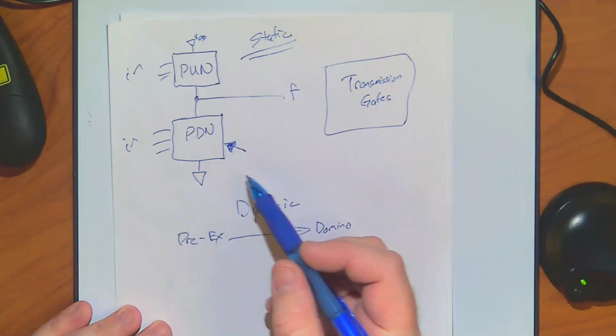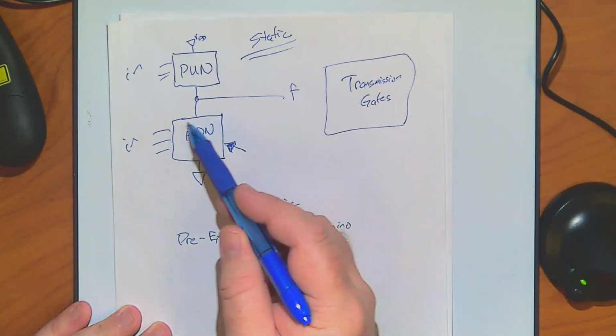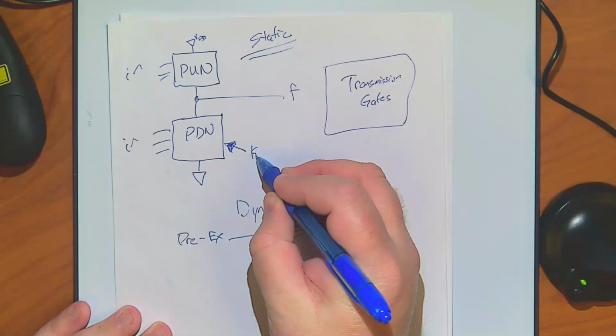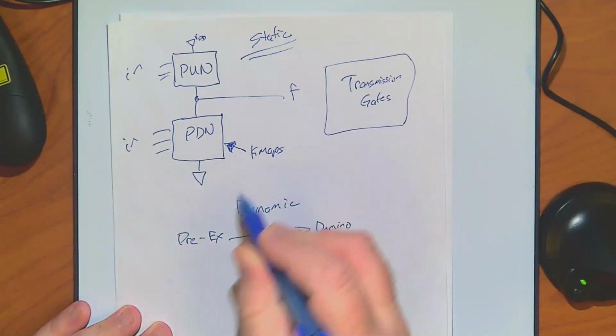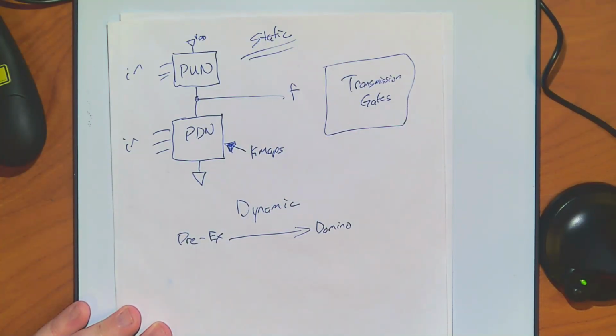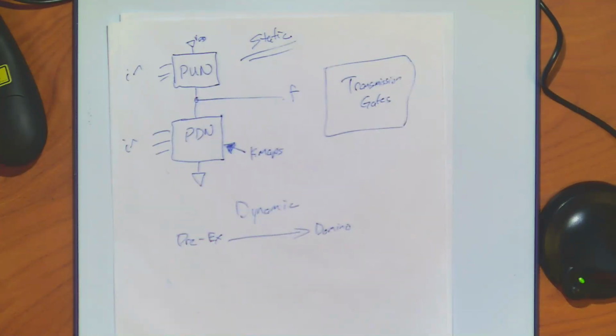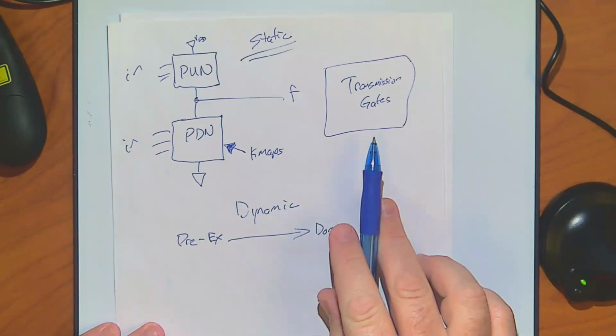Now, the neat thing is when you're actually doing these designs, you can do them with K-maps. And when we get to these pre-charge and then evaluate systems, we'll do one using a K-map to do the design. And obviously, you could use any other logic style you want.